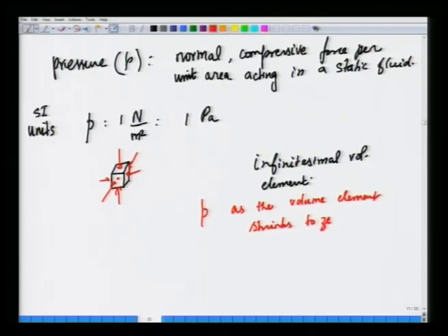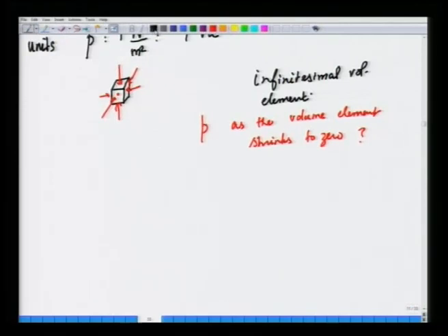Okay. So, the question is, we know that pressure will act purely normally at each and every face in a static fluid, but what is the value of P? Is it the same or is it different along the different faces? We are going to show that it is in fact the same. Okay. So, in order to do this, we take a wedge like volume element.